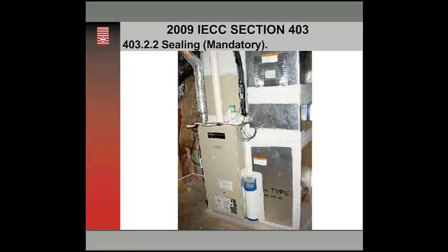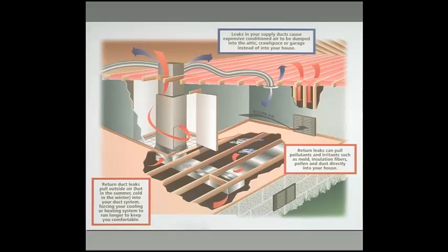Let's move on to the duct sealing sections of the code. In the 2009 code, section 403, air sealing the ductwork is mandatory. And for most of you that are in the southern climates, I don't have to tell you guys, but duct leakage is a big issue.